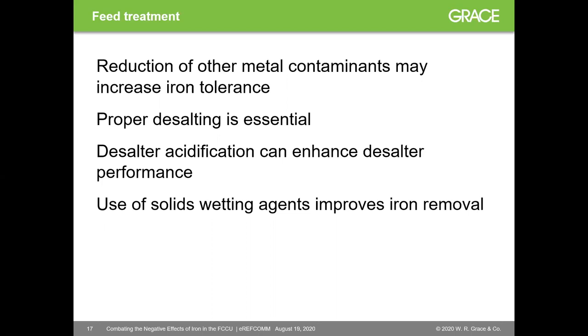Those contaminants tend to end up in the heavier cuts fed to the FCC. This was especially true with the PES case, who charged resid to both FCC units. The use of wetting agents can help drop out solids, including colloidal particles of iron and calcium, from the crude oil.